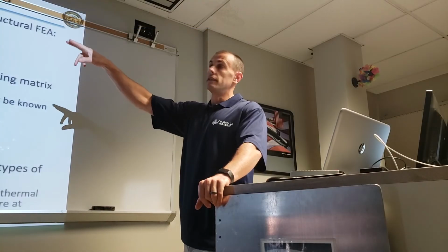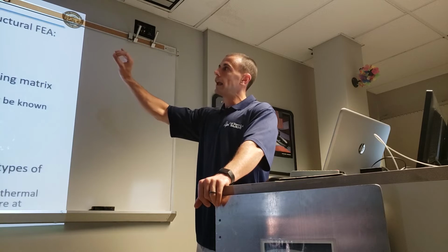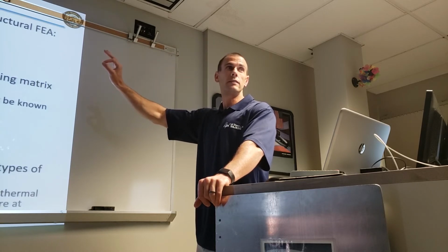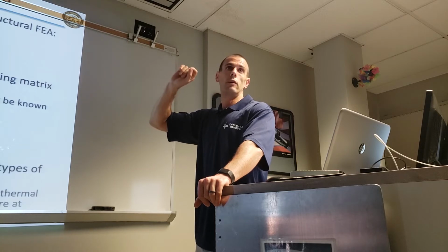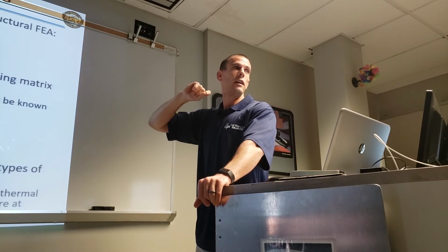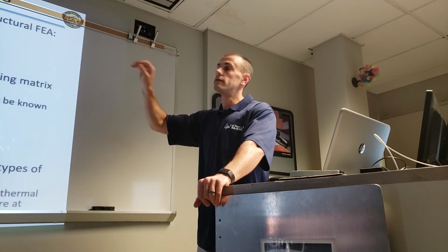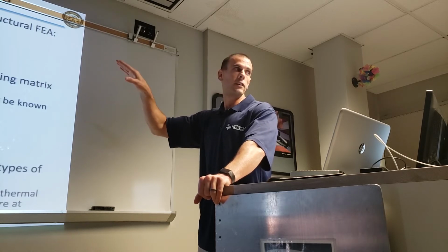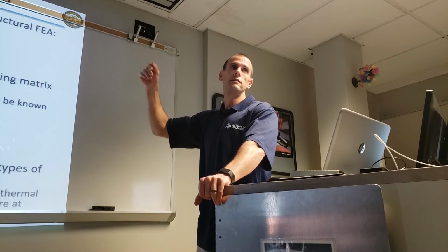In this matrix, you set up where forces are, and you put 0 for the nodes that don't have forces on them. For the displacements, you put 0 on nodes you're constraining, and the rest you solve for. Once you have the stiffness matrix, you can solve for stress.